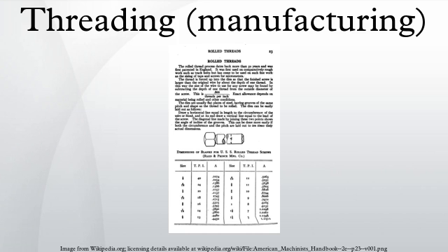The three-wire method is also used when high precision is needed to inspect a specific diameter, commonly the pitch diameter, or on specialty threads such as multi-start or when the thread angle is not 60 degree. Ball-shaped micrometer anvils can be used in similar fashion. Digital calipers and micrometers can send each measurement as it occurs through an interface to storage and as input to software, in which case the table lookup is done in an automated way, and quality assurance and quality control can be achieved using statistical process control.